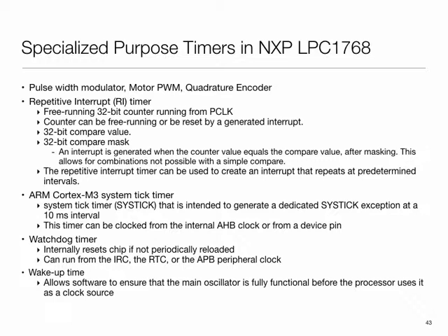And what's the purpose? Someone else? Yeah. Hardware reset. Yeah, but why? Why would I want to do it? I mean, that's the behavior. I load it with a value, it counts down, hits 0, it resets. And why would I want such a timer? Suppose you're waiting for a process to connect and it's not going to come. So you reset your system.